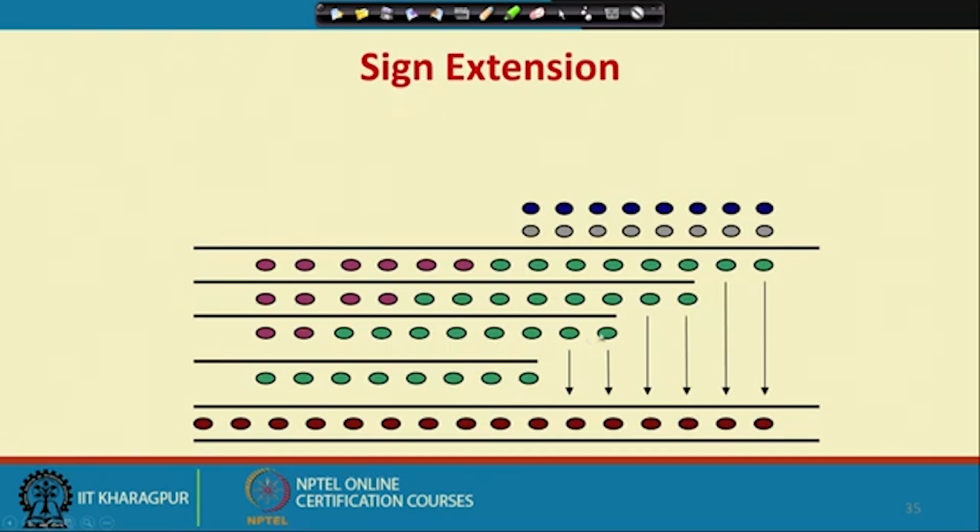So that means the next again is 2 bit. In a generic multiplier what we do? We shift only 1 bit, but here 2 bit. If we choose radix 8, at the time 3 bit shift will be there. Okay. But what about these particular positions?